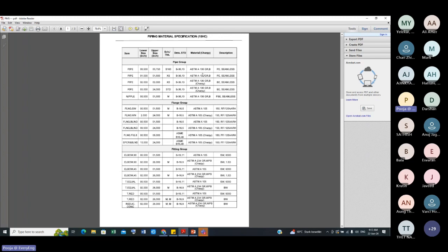So this is also carbon steel. This is also carbon steel, but it will be called by some different designations. Then 150 is class 150, it is a rating. Then what is the facing? It is a raised face. Then we have different facings: raised face, RTJ, like this. Then this is spacer and blind.